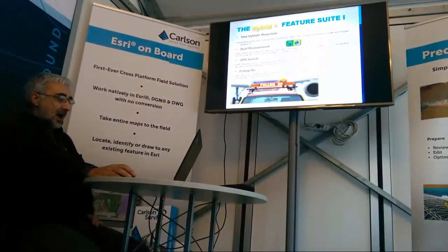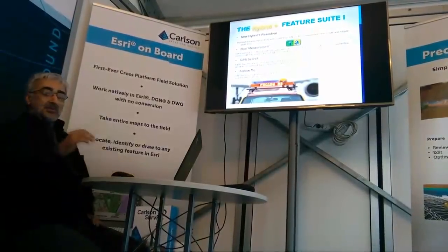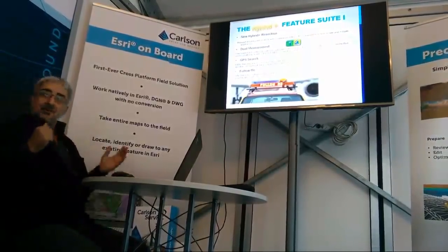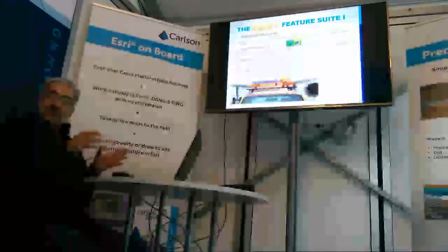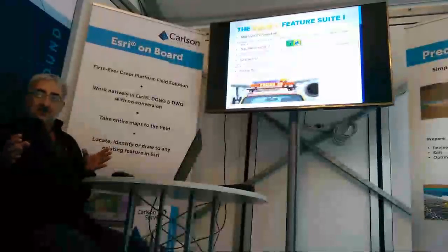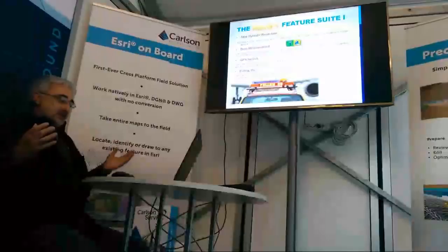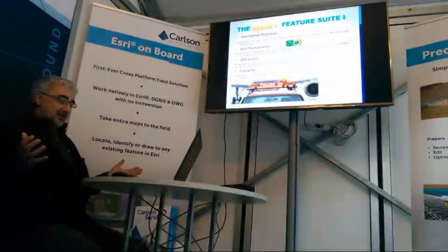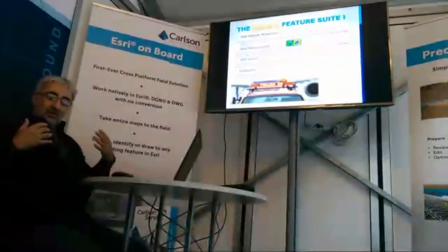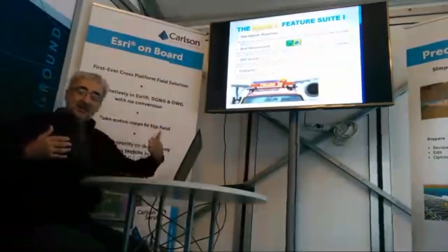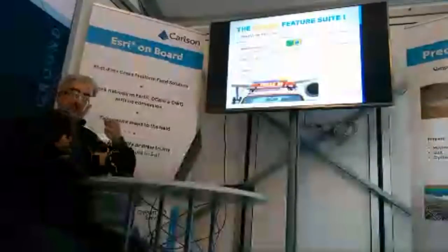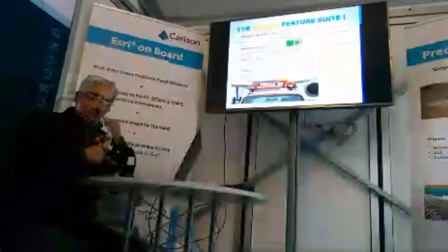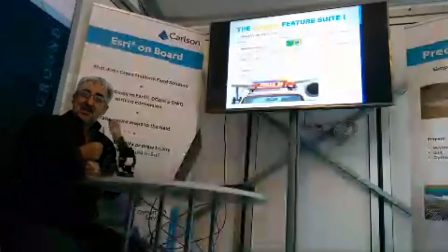We have this new hybrid resection where we are doing a simultaneous shot, measuring both GPS and total station. If we compare the rest of the hybrid software in the market right now, what you normally find is you measure the node with your pole, and then you are prompted to measure the prism with the robotic station, the sideshot, right?